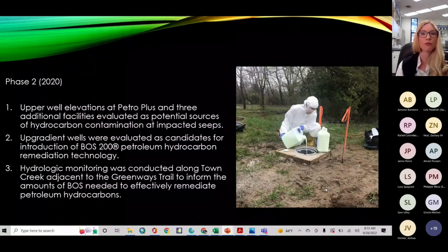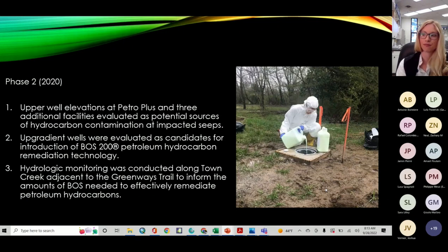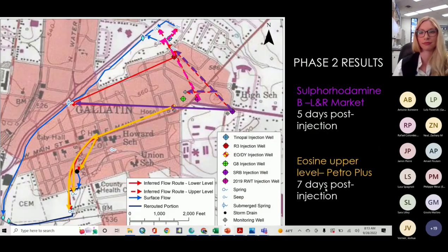And so to test this, we grouted the wells above the injection where the location where the original injection took place, and identified intervals about 540 feet above sea level. We grouted those to effectively close off communication with the lower aquifer, and then injected the tracers. And you can see those results here.